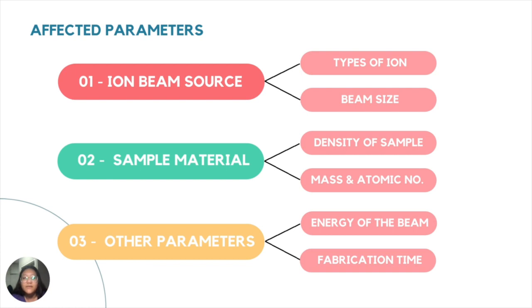However, if it is a gallium ion beam, the mass is higher, resulting in a lower wavelength, so the penetration depth is lower and it has better resolution because the proximity effect will still be negligible. This way, it will be suitable for making small patterns with high resolution. With this parameter, it is the choice to select which result you would want to achieve.